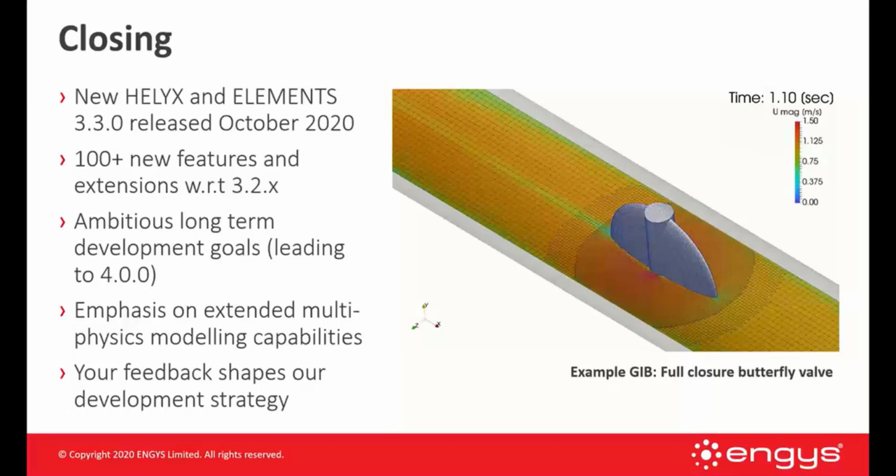Gotcha. Okay, perfect. One question: does the coupled solver for compressible flow work for CHT cases? So I can handle a little bit, and then Paolo might be able to answer this one too. But HELYX CHT, that is a region coupling approach, and at least for enthalpy, that is a coupled matrix across different boundaries within regions. At least the coupled solver that we're talking about here, it's coupled in terms of the momentum direction, so X, Y, and Z, and then pressure. And so it's coupled in terms of that equation, not necessarily multi-region. I think in the future, maybe the coupled momentum component of that could be included into CHT or HELYX CHT, but for now they're kind of separate.